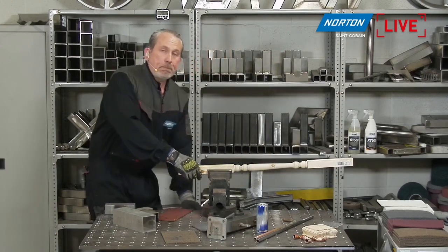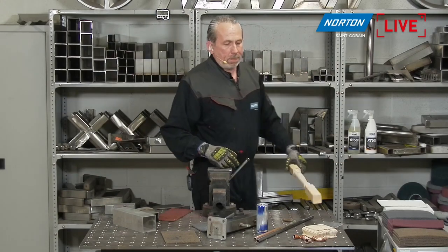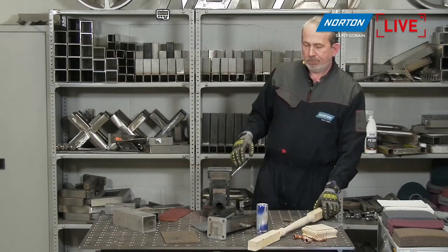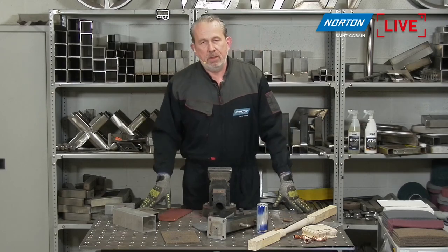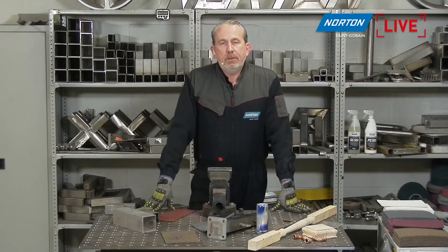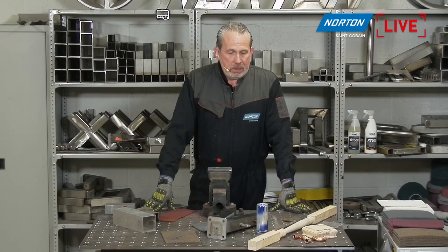And these pads are great, Paul, for the grey ultrafine silicon carbide. They're great for between coat sanding. So if you're going to varnish or paint something and you're doing 2 or 3 layers, you can remove any imperfections or brush strokes or even dust that's gathered on the wood there. You can remove those with between coat sanding of these pads.